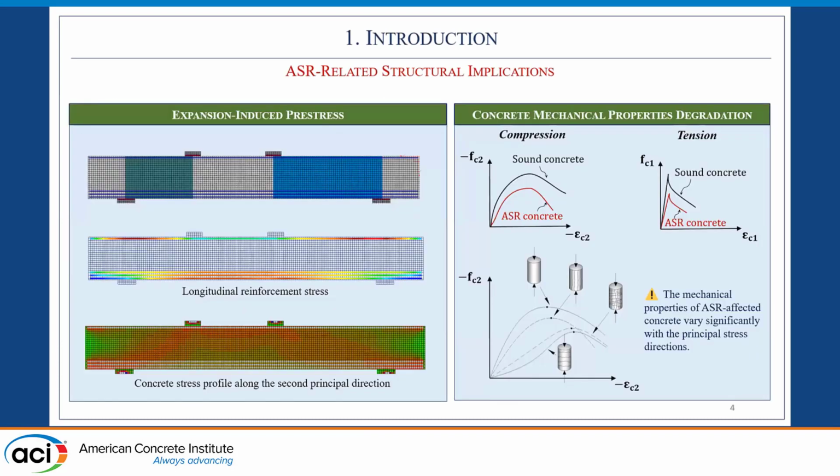In continuing to discuss ASR-related structural implications, there are two distinct mechanisms that we need to be mindful of: the ASR-induced pre-stress that I just mentioned, and the accompanying deterioration of the concrete mechanical properties. Because of the cracking that occurs, the concrete mechanical properties, compressive strength, tensile strength, modulus of elasticity, are all going to be affected. And what we have seen is that they're going to vary significantly with the principal directions.